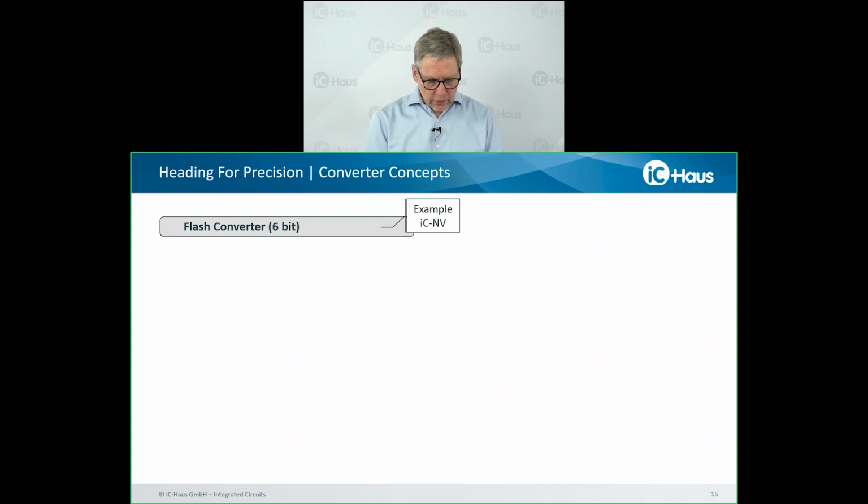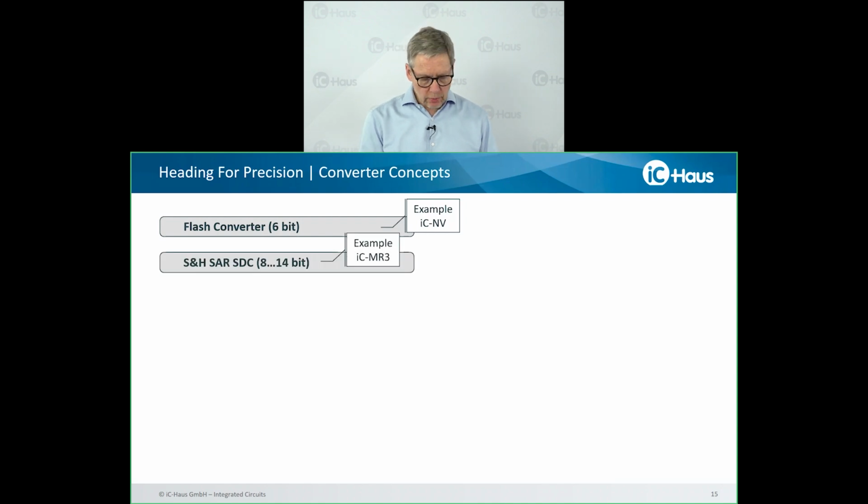Let me give you an overview of contemporary converter designs. Flash converters use comparators that work in parallel and can therefore be quite fast. This concept is usually limited in resolution because chip space is costly. The sample and hold converters are used with absolute encoders, mainly optical encoders, which provide much higher input resolution and much higher input frequencies, of course. There is a conversion time, and quadrature outputs are typically missing, so this kind of converter is not so famous for magnetic systems.